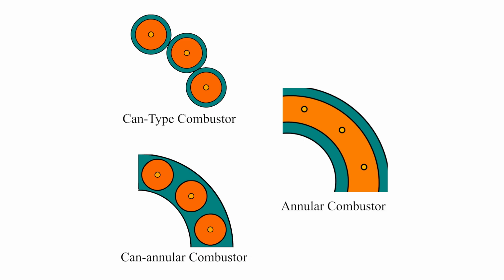Smoke is primarily mitigated by more evenly mixing the fuel with air. As discussed with the fuel injector, modern fuel injectors such as air blast fuel injectors evenly atomize the fuel and eliminate local pockets of high fuel concentration. Most modern engines use these types of fuel injectors and are essentially smokeless.